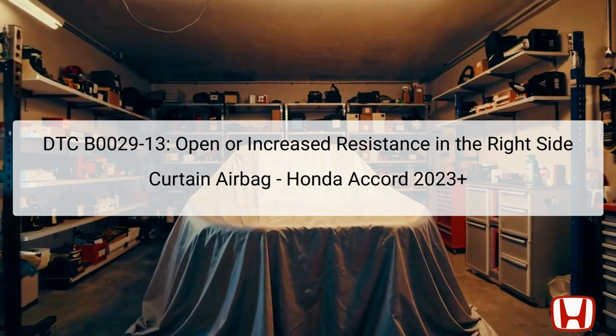When the vehicle's SRS detects a problem, such as an open circuit or increased resistance in the right side curtain airbag, it sets a Diagnostic Trouble Code, DTC. The SRS unit is crucial because it monitors these components' electrical signals to ensure correct functionality. In the case of DTC B0029-13, the vehicle has identified an anomaly in the circuit, storing this code so that technicians can further investigate the